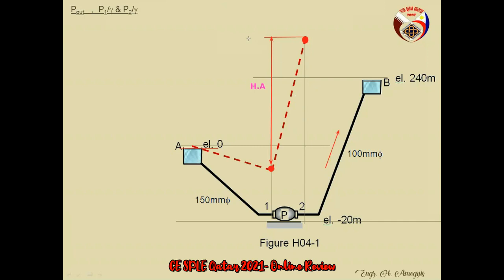Or if there is zero discharge, if there is no discharge, it would be here, just its energy level at point 2. Now, since there is discharge, as we said, it always goes down, so the energy level goes like this. Clear? This principle is very significant and important in solving pipe networks. Notice in the book I shared with you, practice it: when it comes to pipe networks, you cannot solve a problem without drawing the energy grid line. Otherwise, you are just imagining. Okay? So that is a basic principle.